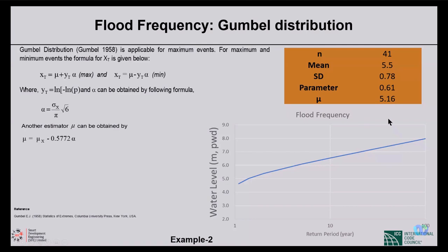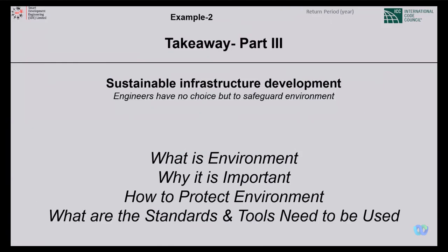with climate change. You have to be careful about it. Which time series, how long a time series you like to use is important. Not only that, the demands by the users. Oh, no, no, no, I don't want 100 years, I want 1 in 1000 years. So you have to be careful about 100 years plus frequency. As a normal principle, at minimum you need 30 years of data to come up with a good shape. The more data, the more reliable your frequency analysis. That we like to talk about.